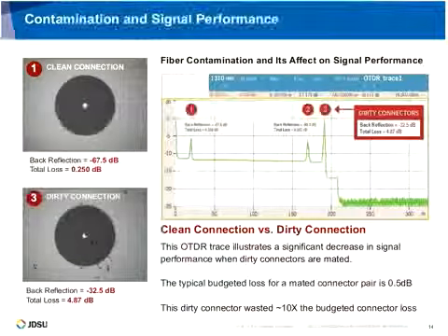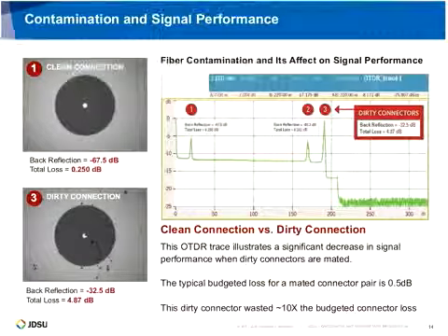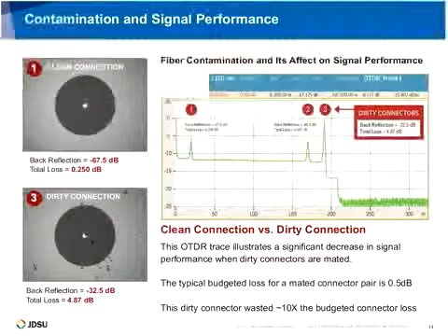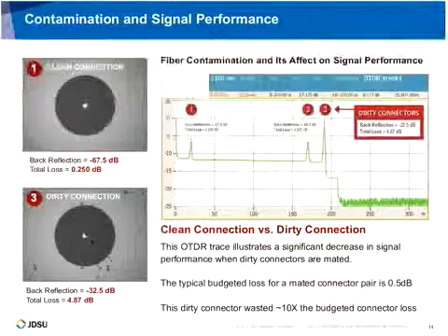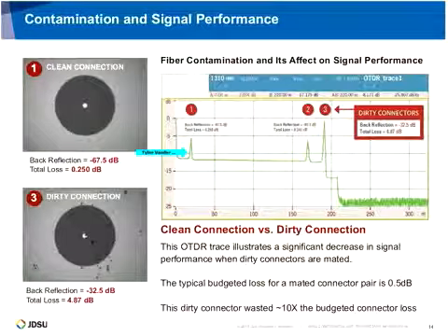And hopefully this slide could shed a little bit of light on that. What I'm showing here on the right is a screenshot from an OTDR. As many of you may be familiar with, an OTDR will measure the loss of an optical signal as it progressively travels down the path of your optical network or your channel. And every time you see a little spike, like this one here, that means there's an event that it noticed there, a reflective incident.